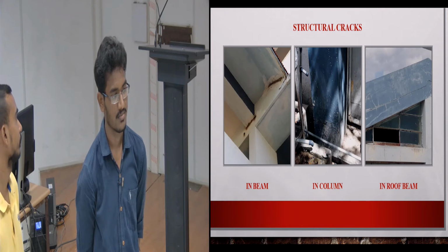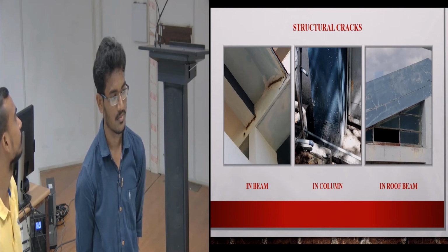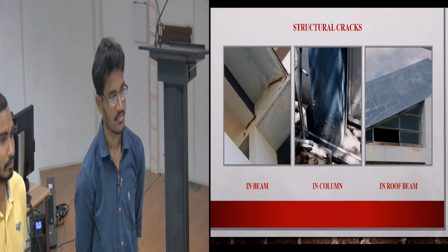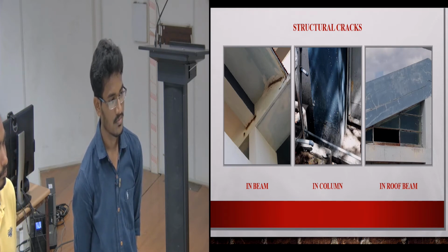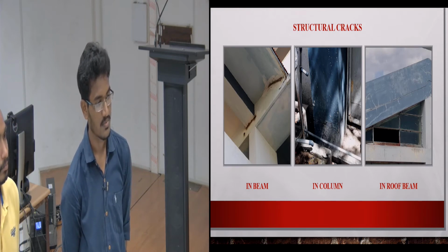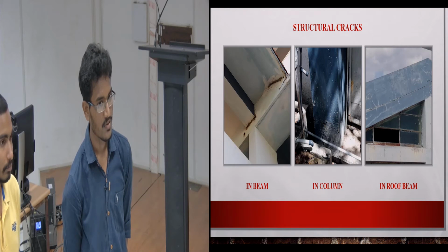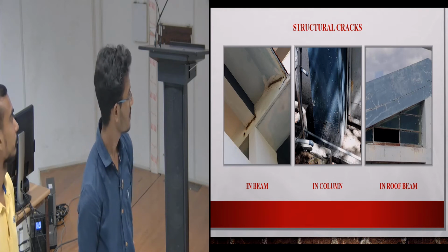They didn't use the proper shoe to interconnect, so they just concreted and dismantled. Because of that, there is no anchoring. This is quite a common mistake in all construction places. They don't place the shoe of the column properly. That's another observation: either the rebar didn't go all the way, or the rebar is corroded.